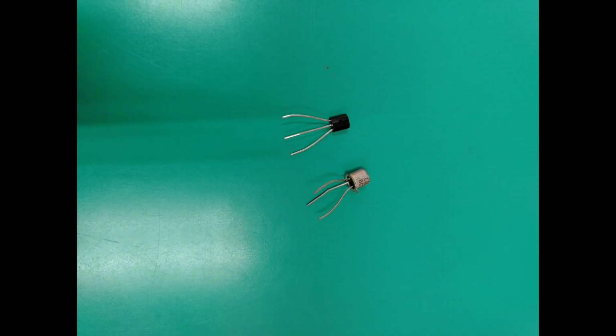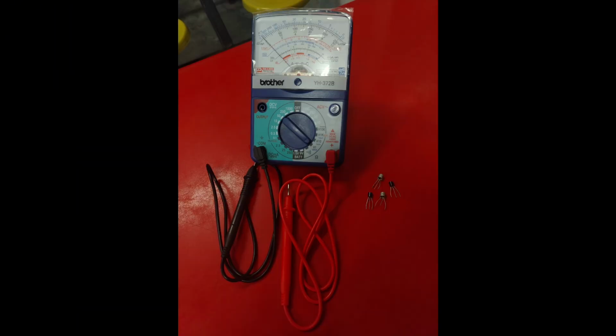Now look at the transistor. It has a flat side. When we face the flat side toward us, the pin arrangement is usually emitter, base, collector from left to right. However, this is not always 100% accurate because different models may have different pin arrangements. So, we must confirm using datasheet or testing method. This method is fast, but for accuracy we move to the second technique.